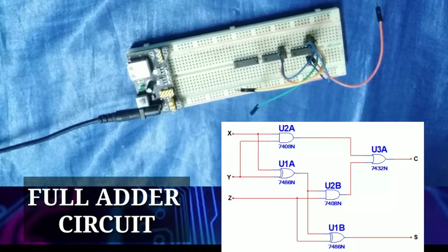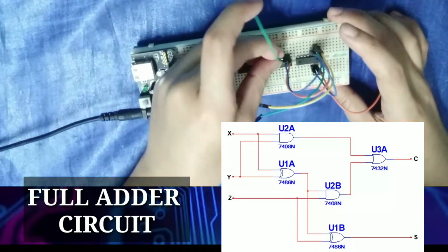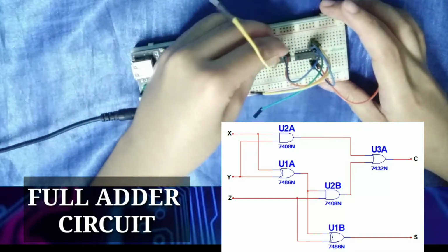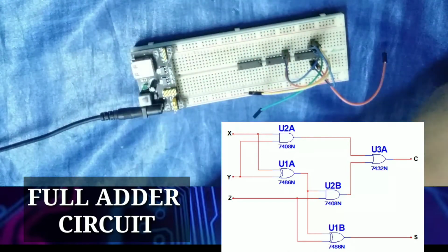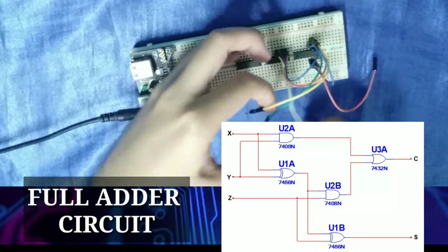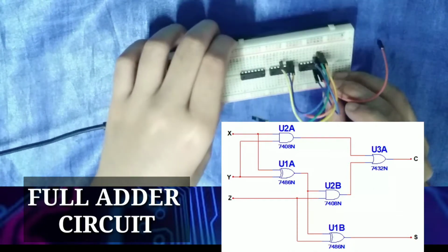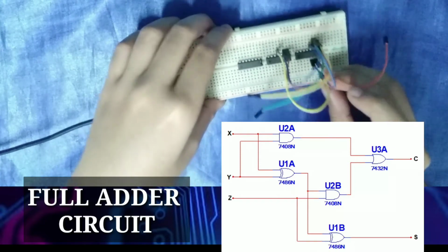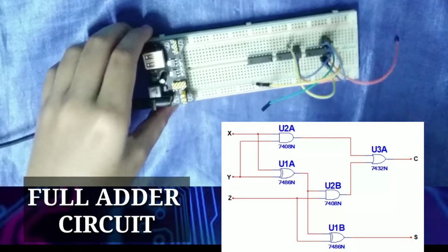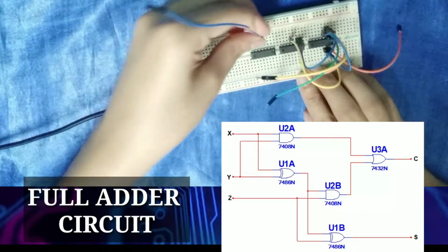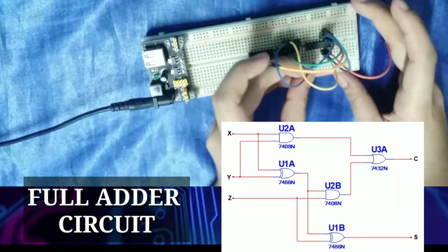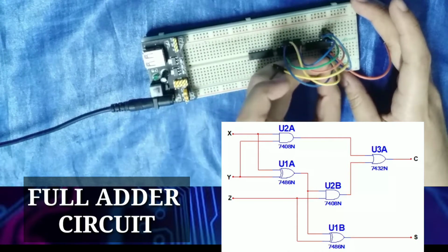Now, let's connect the fourth pin of the 7408 to the 13th pin. Let's get some appropriate wire here to the 13th pin of our 7486 integrated circuit. Also, let's connect the fifth pin of the 7408 to the 12th pin of our 7486 here.